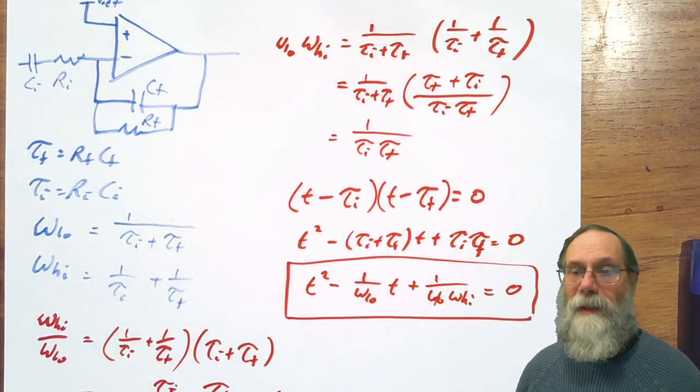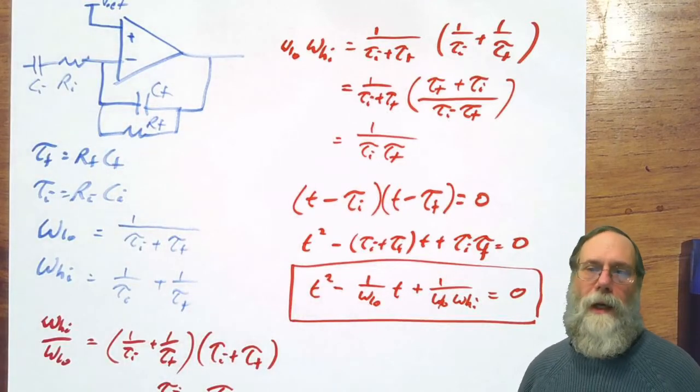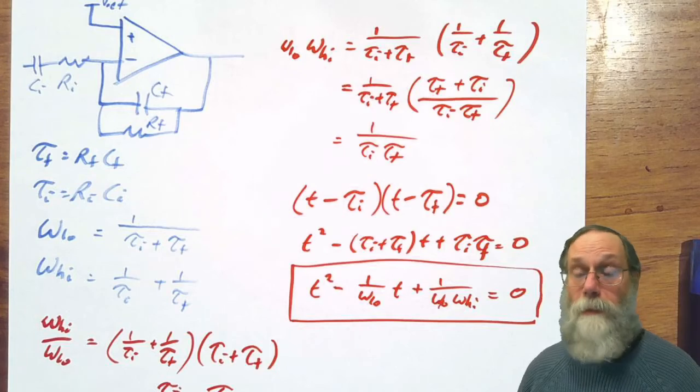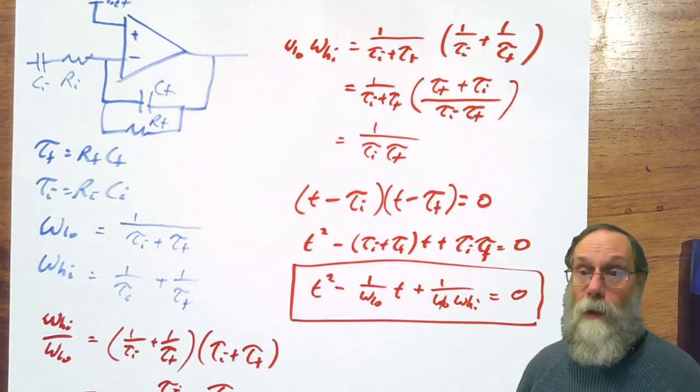That turns out to give you the easiest control of the gain, and generally an easier way to think about it, because of the simplification we did before, when the corners were really far apart and we just stuck one corner frequency here and one corner frequency here. That's the way we chose it.